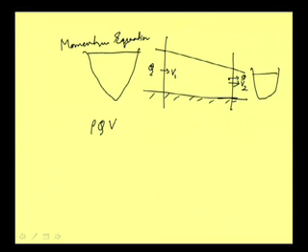Then if we multiply it by the velocity v1, we get the momentum. Of course, this rho we can write in terms of unit weight also as gamma by g. This is also one way we can write, and this is the momentum, but with that we need to put the momentum coefficient that we discussed earlier.